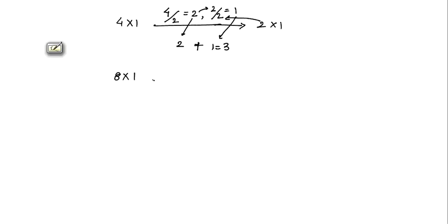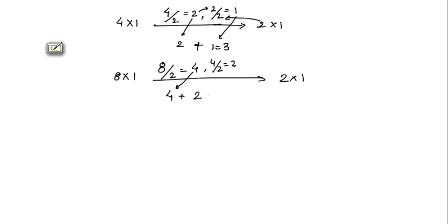Then we implemented an 8:1 multiplexer using 2:1 multiplexers. For this, first we divide 8 by 2. Answer will be 4. This 4 will be taken out. Now this 4 divided by 2 equals 2. This 2 will be taken out. Now this 2 will be divided by 2, and this 1 will be taken out. Total 7. In the last circuit we saw an 8:1 multiplexer requires 7 2:1 multiplexers.